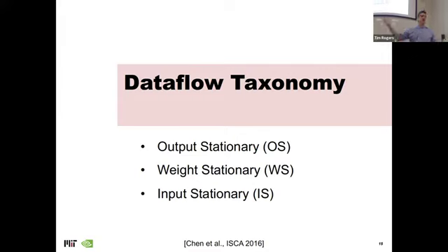And we went through the fact that data flow is one of the main mechanisms. They don't use a register file that everyone has to communicate through. They will chain together processing elements and share data among those processing elements. But then the challenge becomes, how do I map all of the different parts of my deep neural network into these processing elements? GPUs are kind of easy, right? Things go into shared memory, things go into the register file. That's where the storage is. When I have bespoke processing elements, I need to decide what stays in the processing element, what goes out on the interconnect that connects them, and what I am reading more globally from the buffer.